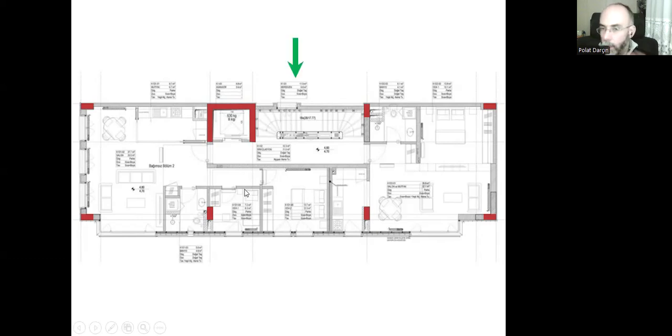And during this lateral movement, since this part becomes heavier, it doesn't want to move, or it moves slowly because it's heavy. However, the rest of the building, since it's lighter, needs to sway bigger. It needs to make a bigger sway.